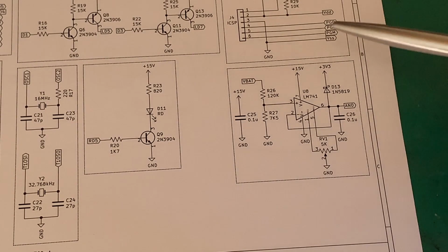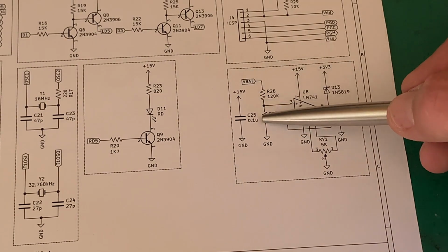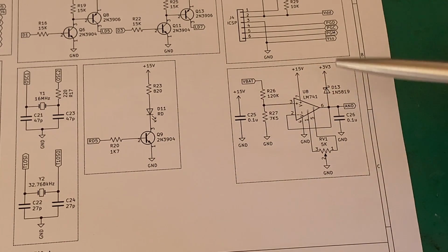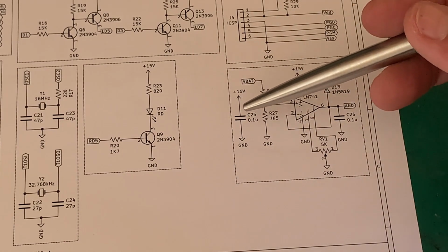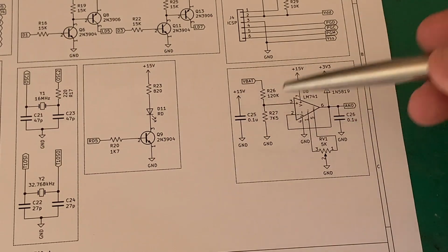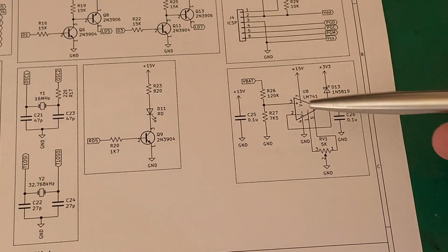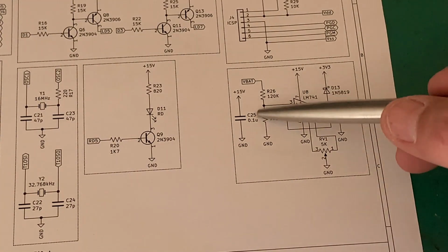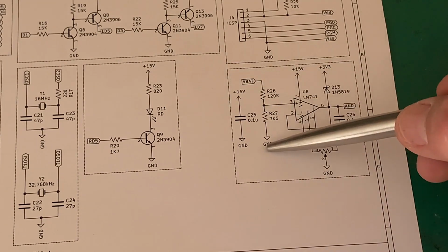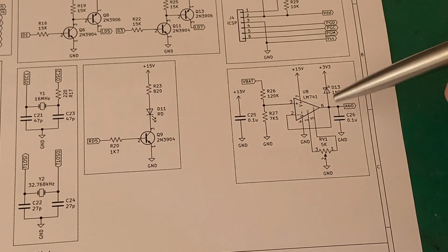We have the 3.3 volts. So what I'm doing is I'm dividing the battery voltage down. If that was 56, I will have 3.3 volts out here, and so on linearly as the battery goes down. And the 3.3 is important because we're going to measure this with a microcontroller. So I needed something to buffer the main battery circuit from our microcontroller.